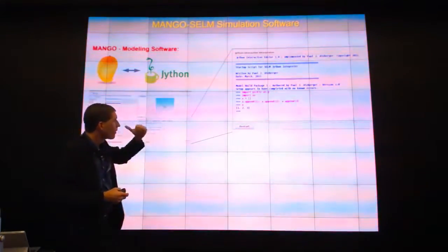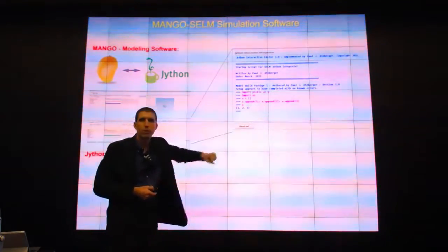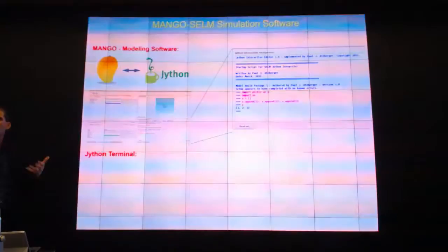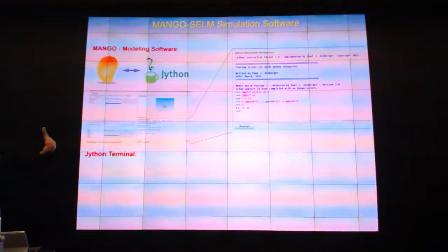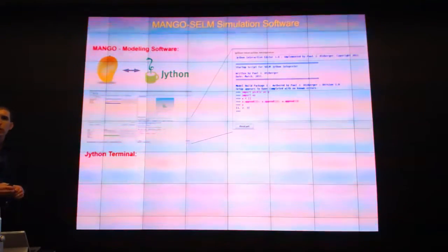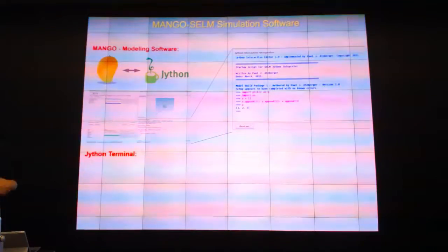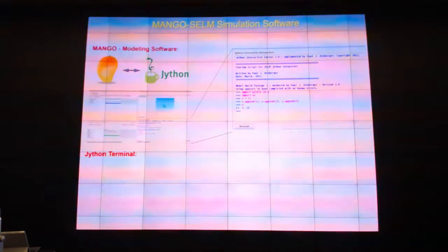A lot of the functionality that you see in the graphical interface, I've written Jython wrapper packages that allow you to make function calls and essentially do anything that you would do by pushing the various buttons. You can do it through scripting commands in Jython, which would make life a lot easier, I think, in setting up more complicated models, where maybe the interactive part would just be to do a little fine-tuning at the end.